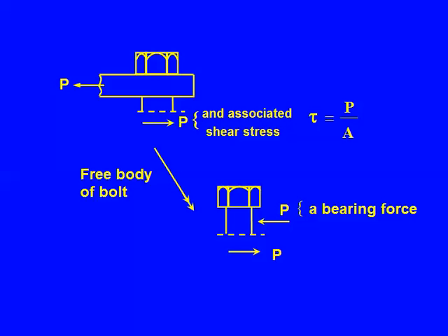Well, there's only physically one location where it can show up, and that's the plate pulling against the bolt, and then I'll show the force here. It comes in like that. We like to label things, and we call that a bearing force. It's the plate bearing on the bolt. Okay, so we've got some more information. We'll come back and look at design rules for these issues.